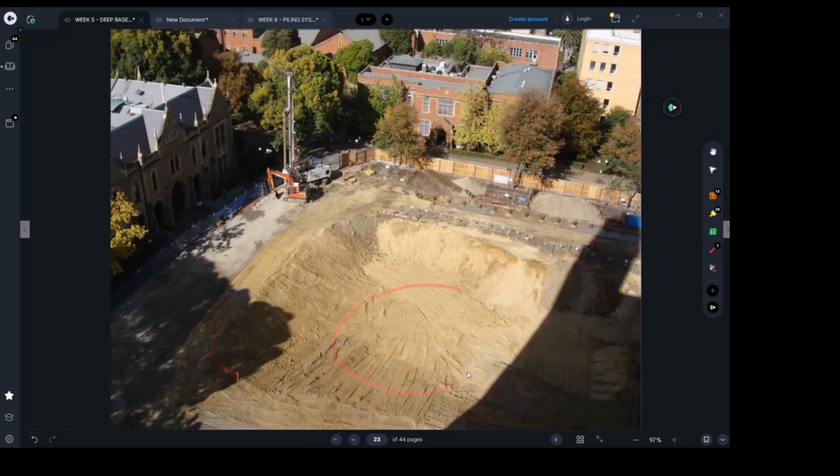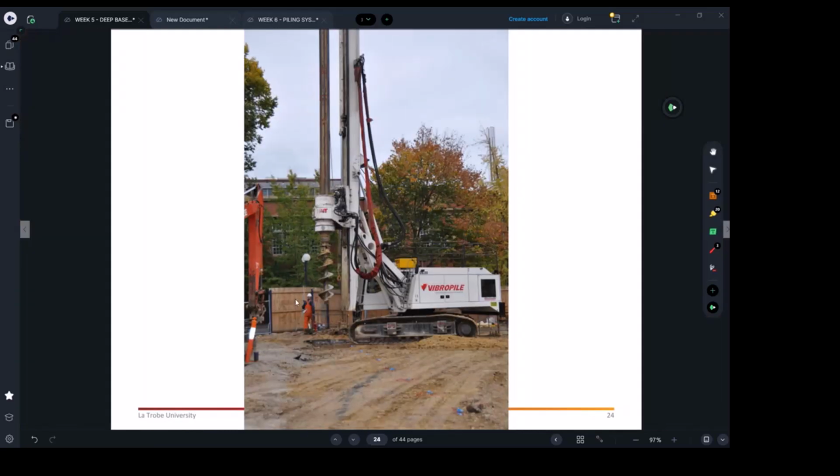They wanted to take some material away because all these materials need to be transported to specific destinations, depending on where the council wants to take it. So the builder wants to really get some material out. They want to start. But remember, they are still far away from the basement line. They cannot excavate at 90 degrees up to the retention system. It's going to collapse, as we discussed.